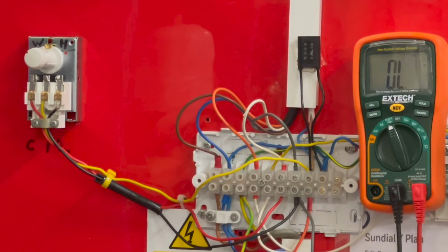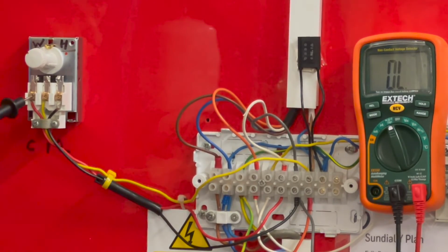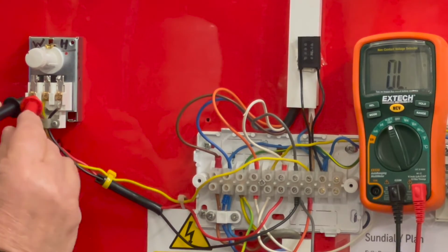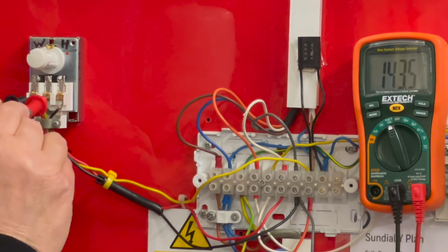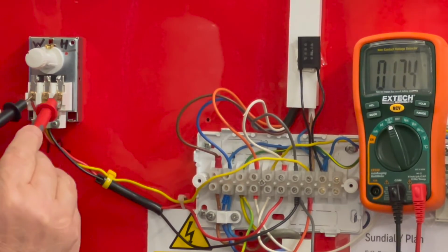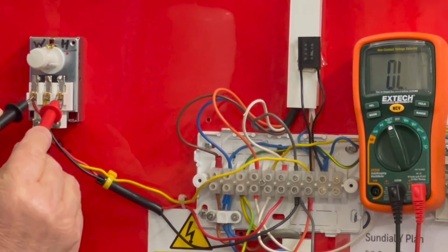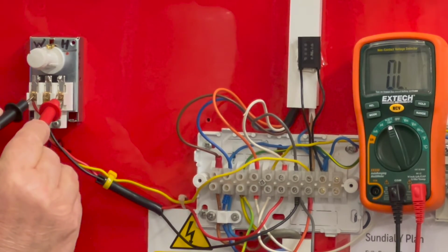So now we're going to test the new cylinder stat, and as always we've powered off, we're in ohms with the buzzer. There you are, that proves it. So we'll put common to 1, which is hot water on, should buzz, and obviously the other one, terminal 2, should not. So let's do 1. There we are, that's fine. And that's now silent. Open line means at least 1,000,000 ohms.